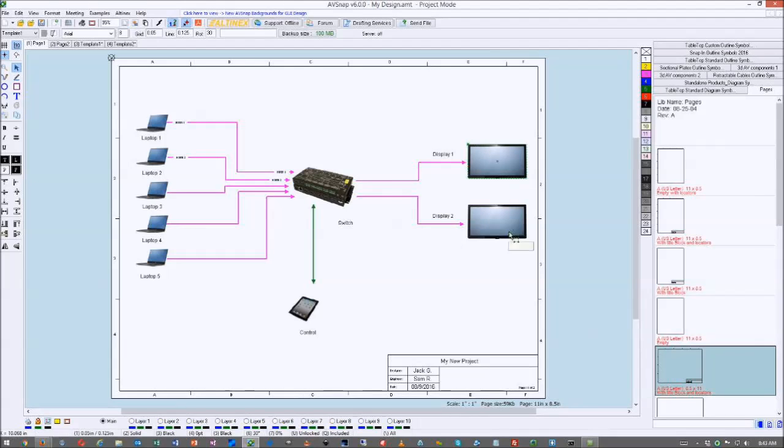So here's 1 unit. So instead of keeping this now, I'm going to go ahead and delete it and copy paste here. So now we have 2 symbols. Why do I want to have symbols? You'll find out in 1 second, because I'm going to take this line, and I'm going to move this line closer to the symbol and let it go. And it's going to ask you, do you want to add a snap point? If I say yes, we just create a snap point, and this is attached to the snap point. So now you have a more intelligent system that can track what's connected to what.